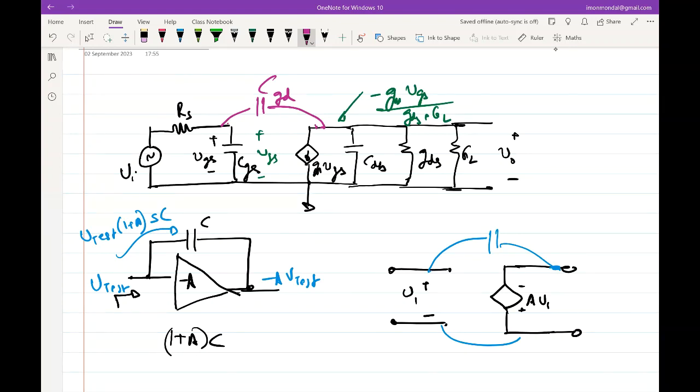So when dealing with the Miller effect, we are assuming that it's a voltage controlled voltage source, so putting a capacitor or any contraption for that matter doesn't change the output voltage. But in our case, it's not a voltage controlled voltage source. It's better modeled as a voltage controlled current source with some resistance attached to the output. So if you connect something to the output, you are changing the effective resistance or impedance of the output, which means the voltage is changed, right?